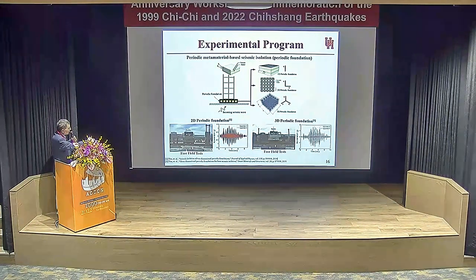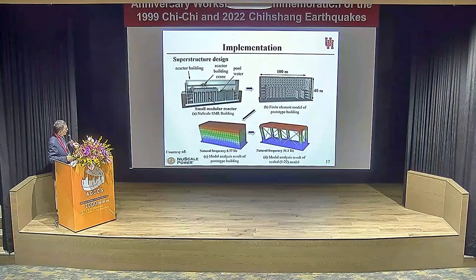At the top is a steel member. As you can see, the response right at the top of the structure. For this case, with metamaterial foundation, the vibration is so small, reduced more than 90% when compared with conventional RC foundation.